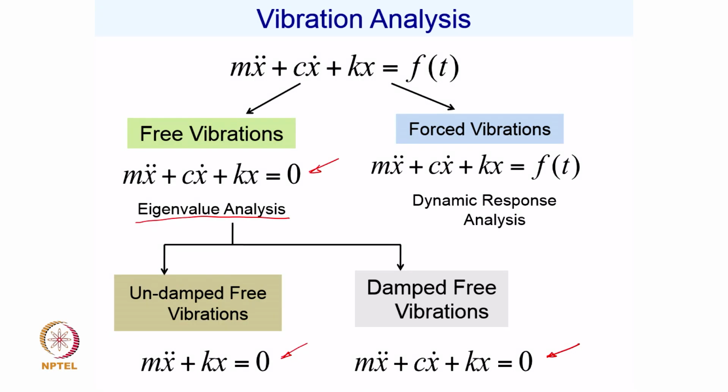So, when we define the excitation function for our mechanical system, for example, the engine operating speed, we define this excitation function, maybe F cap cos omega t, and then this omega is your excitation frequency. Now, once the rotational speed is fixed, to avoid resonance, obviously you would like to know what your omega n is, the natural frequency.